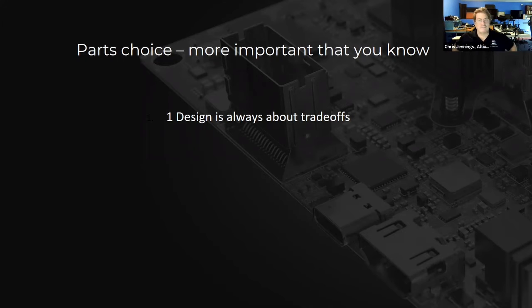Again, that brings up, as we've said, that parts and components don't just live in the schematic. They have to live in the PCB realm. So you need to understand how one parts choice affects both the schematics as well as the PCB. For example, with the RF device, not having to have controlled impedance means the board can be made a lot more cheaply.